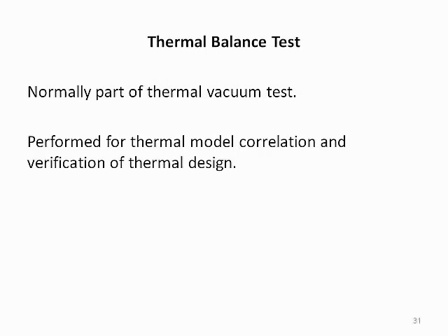Thermal balance testing is usually conducted as part of the thermal vacuum test. The objective of the thermal balance testing is to gather data for thermal math model correlation and verification of the thermal design.